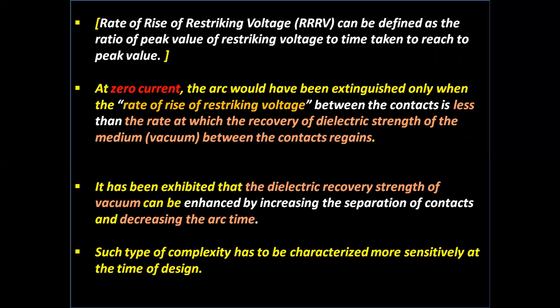At zero current, the arc is extinguished only when the rate of rise of restriking voltage between the contacts is less than the rate at which the dielectric strength of the vacuum between the contacts recovers.